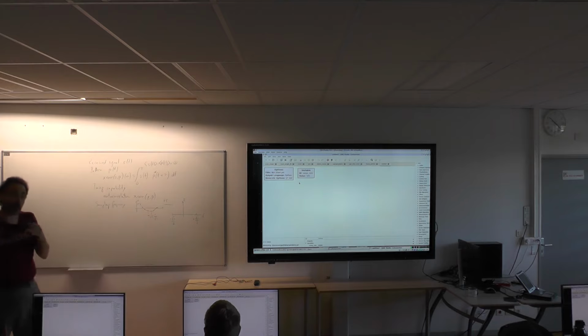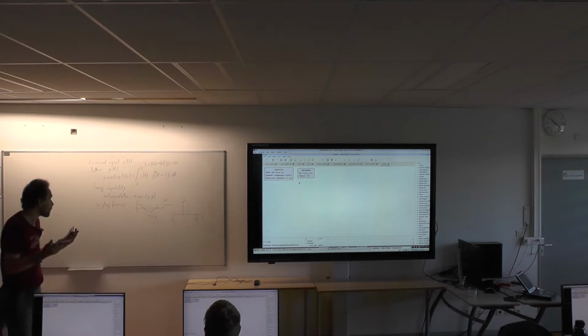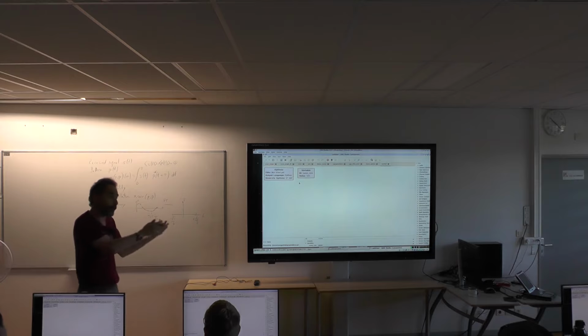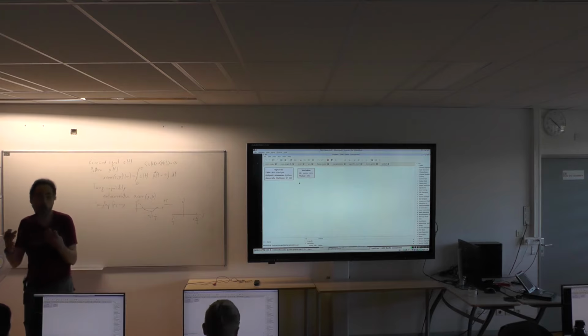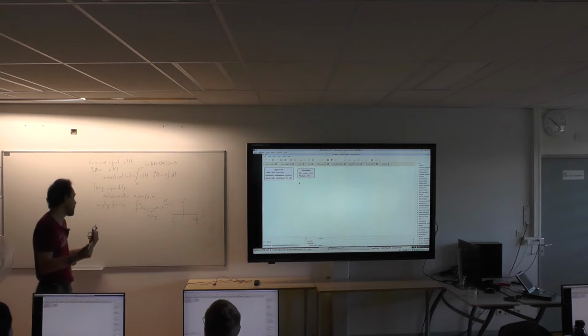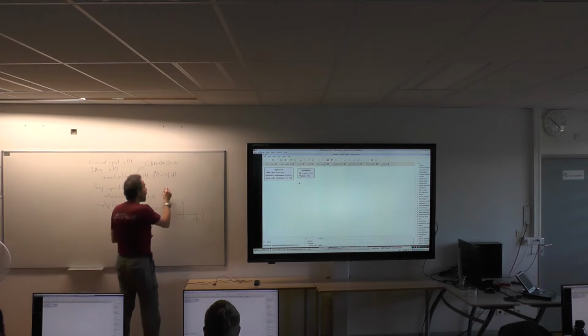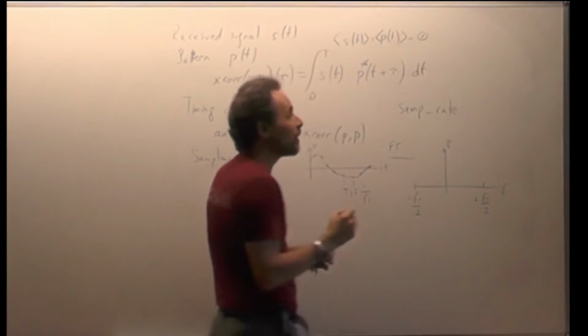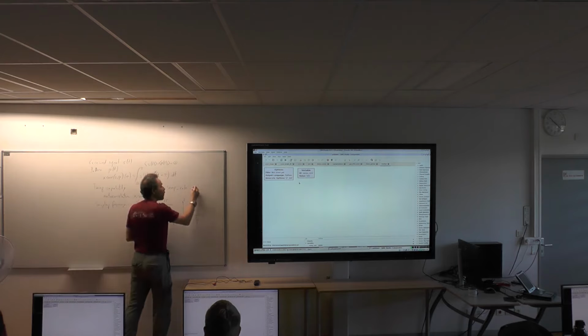Now, at first, we're going to work only with synthetic data, so the sampling rate is just arbitrary, something with respect to 1. If you have real hardware, as we're going to do by the end of the lab session, you need to inform GNU Radio what the actual hardware sampling frequency was. And because this is all Python programming, you actually have a default variable which has been defined by GNU Radio, and the default value is that this quantity is equal to 32,000, a random value that was selected.